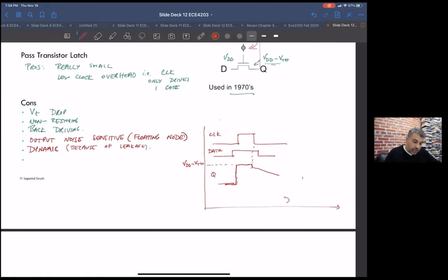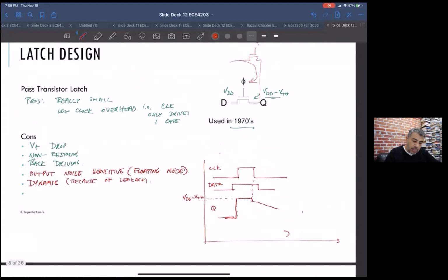And then finally, notice we are driving a source or a drain. We're driving a diffusion here, and putting the value on another diffusion. Most of the time we've been driving just fully capacitive gates, so just driving a diffusion could have lots of problems.